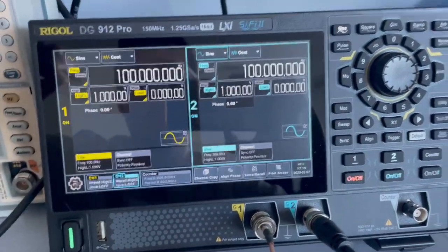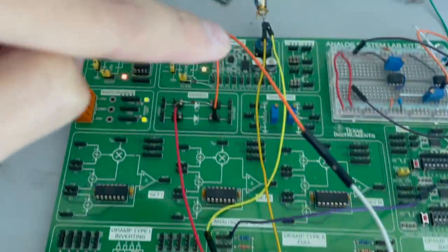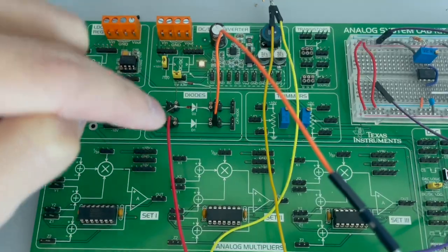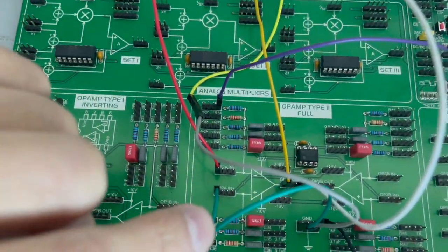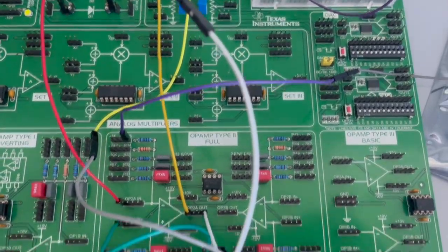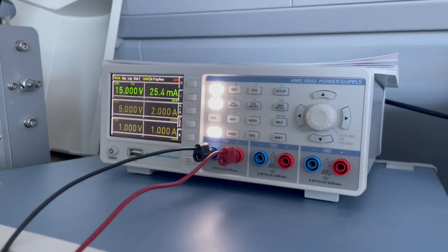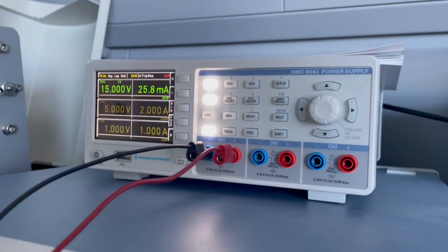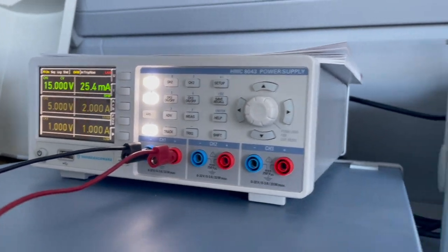Okay, so the signal from signal generator goes to 1K resistor, and the feedback line is going to be connected to the cathode. Make sure that from output it goes to the cathode, and the anode goes to the input of the amplifier, okay? And plus goes to the ground. And set your signal generator to 10 or 15 or 20, change it accordingly. If you're gonna have clipping, increase the biasing up to 20.